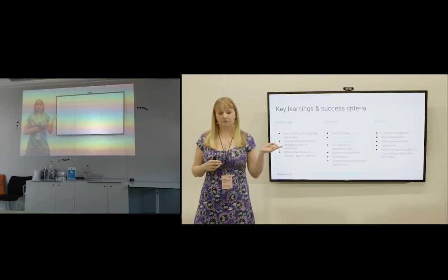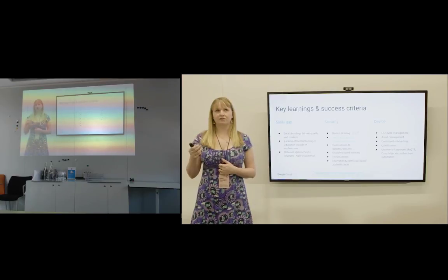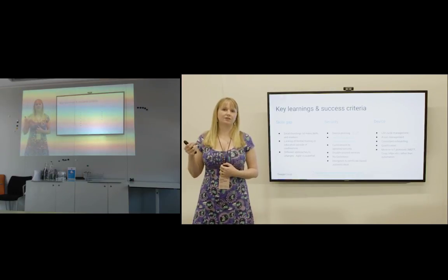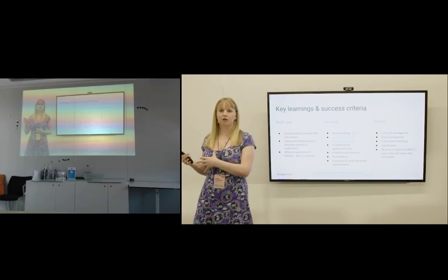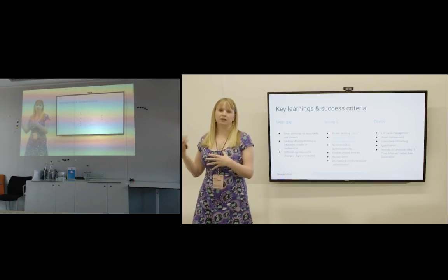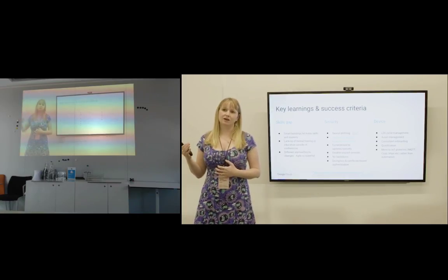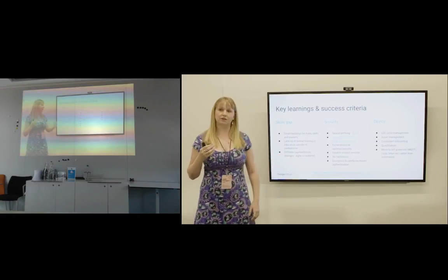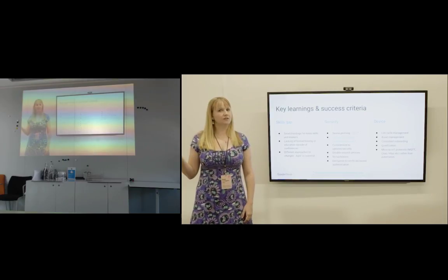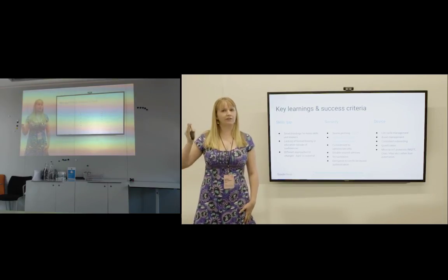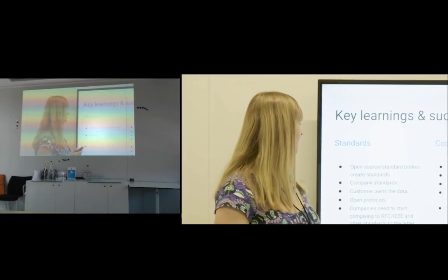And the other one on the device side is that these devices have been built and designed around protocols that are designed for local use. They're designed for being used within a building. If you're trying to connect these into the cloud or outside your building, you need to start moving towards IoT protocols like MQTT rather than using things like BACnet, because that kind of traffic is not what you want to be going over the internet.